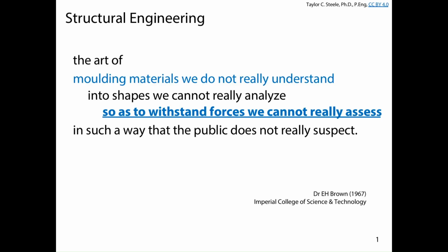And what else was important there was we represent these loads more or less as uniformly distributed over the floor area. We talked about how to trace uniform loads down through the floor system in lecture 3 earlier in the term, and so it's convenient for us to treat these as uniformly distributed loads. And as long as we're capturing that maximum moment and shear, that's all that is really important.